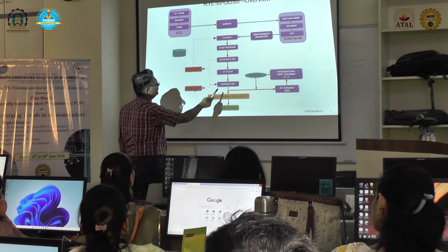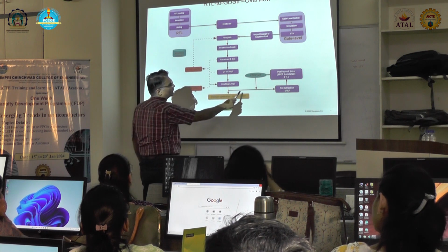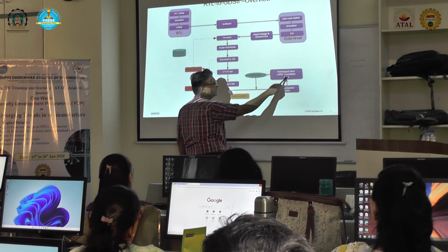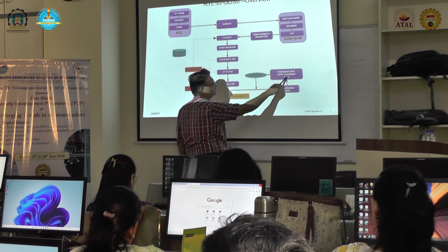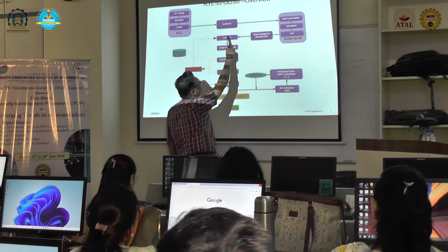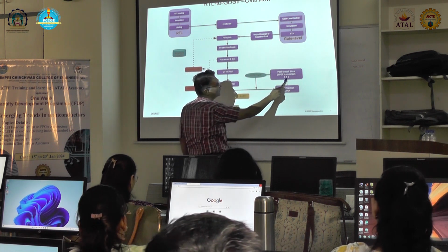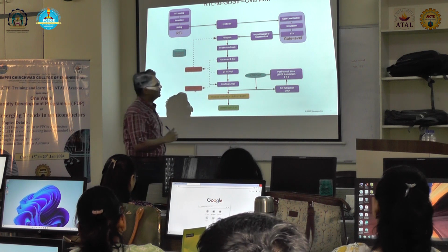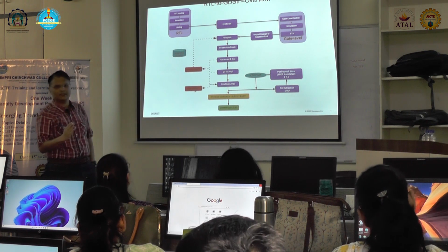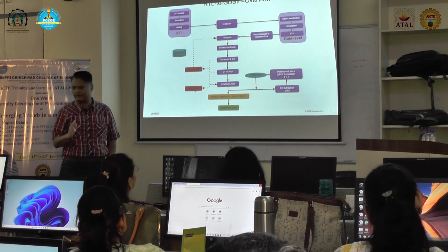Similarly, we also do a static timing analysis. If the static timing analysis fails here, then we have to go back to this stage. So from here again a timing check is performed to see whether the circuit is working at the desired frequency also.